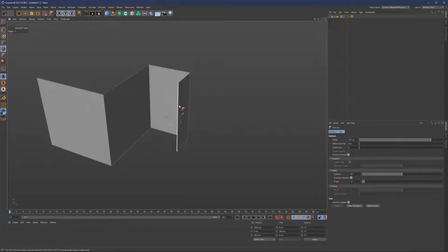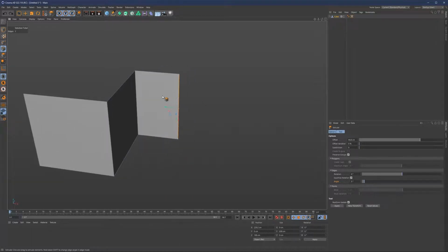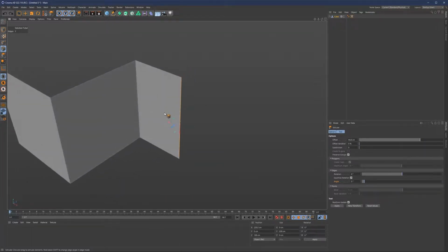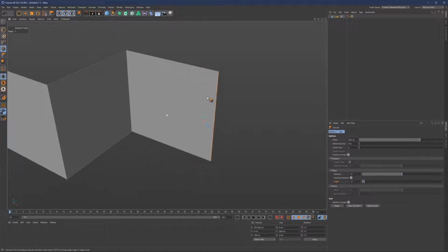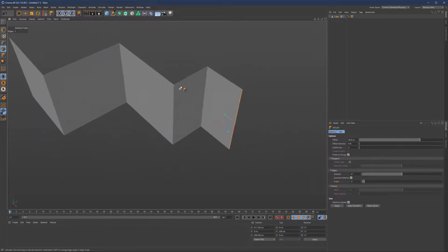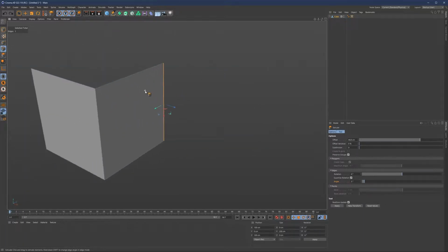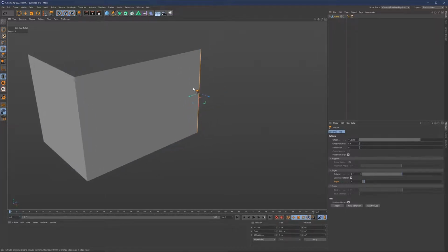The only thing here is that it's going to extrude on a specific angle. What you can also do if you want to have more control, you can actually use the Control key to extrude the edges in the direction where you would like. So this is also something very useful. An additional thing that we can do, so let's say use Control, extrude the edge like this.